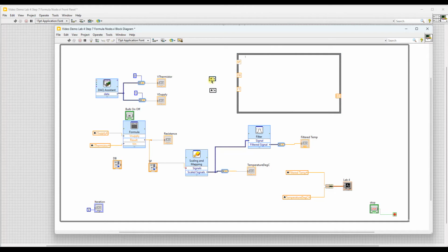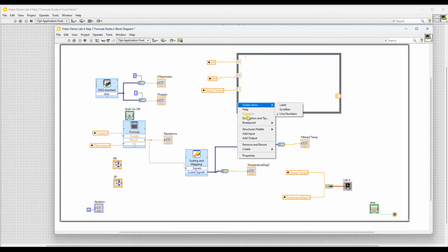So let's just copy and paste these. And the top one is going to be the set point, and I have a set point slider. Okay, I don't have to wire this because I'm using a local variable. So set point, and this one's going to be the deadband, and this one's going to be the filtered temperature. And now we just connect these, and our program will use the variables in the boxes here, not the ones outside. These are the input variables, and this output variable, I'm going to add heater out.